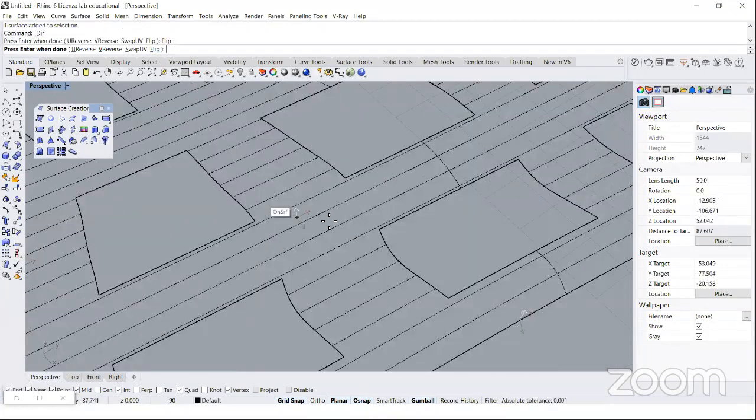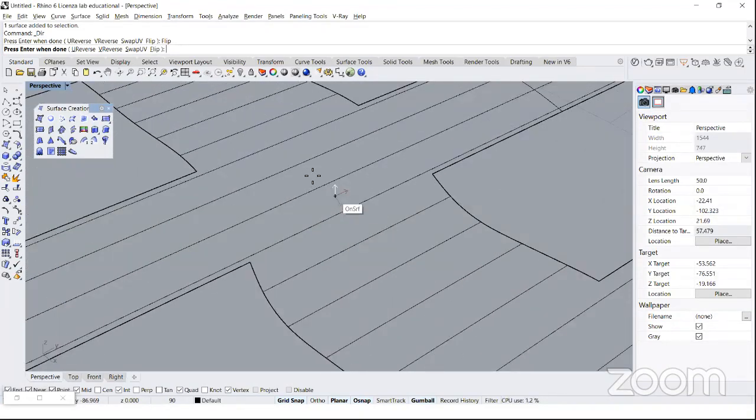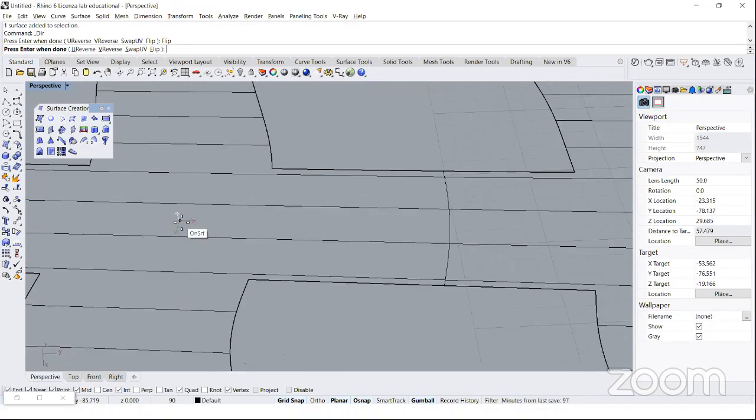If I just flip, what I'm flipping is the white arrow. Okay, I'm not flipping the internal coordinate system. I'm flipping just the normal direction, which, by the way, in this moment would be enough to obtain the white face of this surface pointing up. But this, allow me to say it, screws things up more than before, because we don't have a correct internal coordinate system. You see that the white arrow is pointing upward, the red arrow is pointing to the right, but the green arrow is going down instead of up.